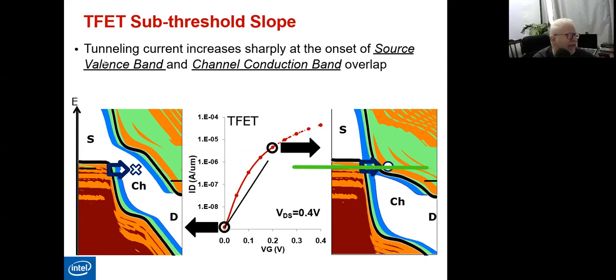Now, as you can see, the effect of the gate voltage is that it has narrowed down the channel. So in the first stage, which is the thermodynamic equilibrium stage, the channel was relatively wide. However, by applying this relatively high gate voltage, which is above the threshold voltage, the channel starts to be narrowed down.